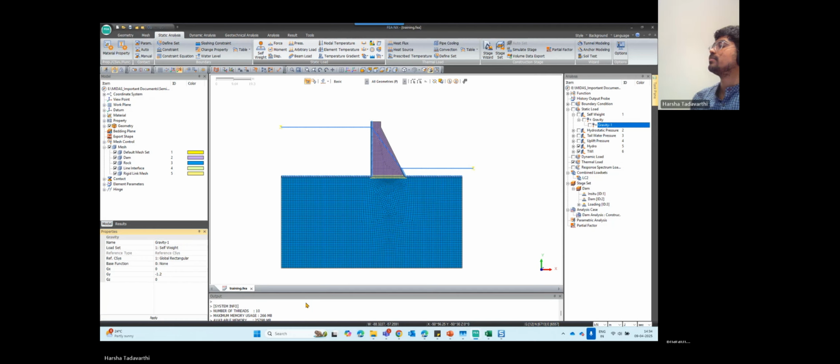So we have the resisting force. Sorry, that's the resisting force. And let's say, and now we have the force applied onto the dam, right? So we can actually get the applied force at each and every node of the dam, and centroid multiplied by lever arm. Yes, we can get the applied forces as well as normal forces at the interface, and we need to export that to Excel sheet and then calculate the lever arm distances, and then we will be able to calculate overturning factor of safety as well. Yes, it is possible just by extracting the results and thereby doing some calculations on Excel sheet.